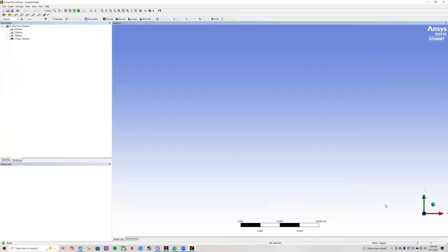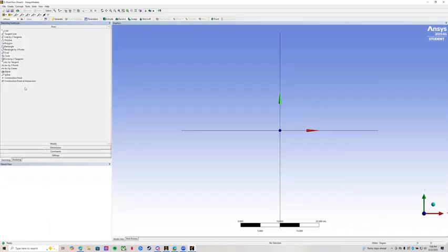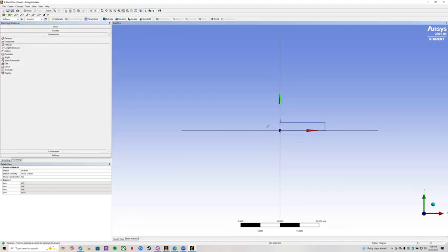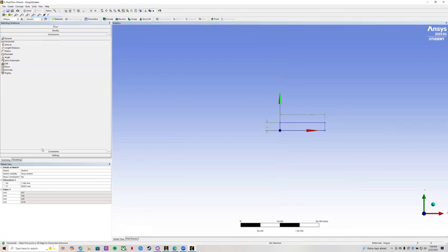We're going to click on our Z-plane, go to sketching, make a rectangle, and we're going to go from our origin again, just for simplicity. Go to dimensions, vertical, just like before. In this case, we are going to downscale our pipe a little bit for the Couette flow. It just makes it a little bit easier. Make sure to switch your units to millimeters.